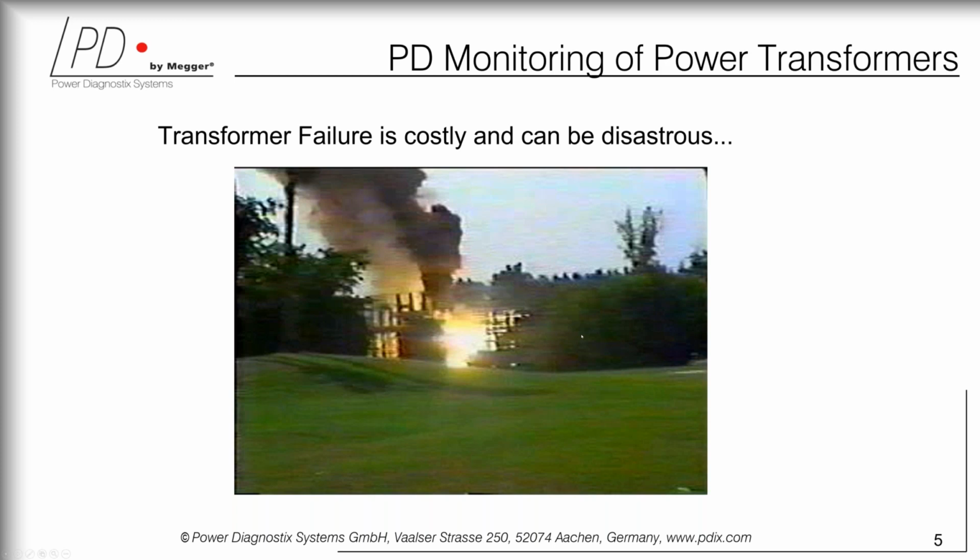But of course, this is at start when they are first conceived, and definitely the power transformers have a life of their own. And maybe here you can see a dramatic example of such a life when there are issues generally caused by the quality of the insulation within the power transformer, by problematic manufacturing, and of course that can lead to specific explosive gases being built within the tank, even within the bushings, etc., and then explosions can occur.